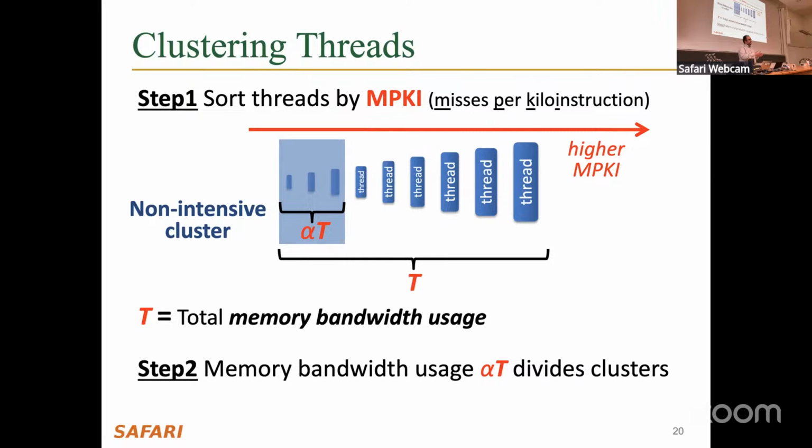So if we try to accelerate that, then we can keep the core active, which in the end is going to help. So it's very hard for me to imagine an application that has too many off-chip memory requests. It can actually be L1 cache accesses, which, because of the locality, are hitting the L1. But if the application has too many off-chip memory accesses back to back, it's very hard for me to believe that that application is utilizing the cores well, because the computation latency is much lower compared to the memory accesses.